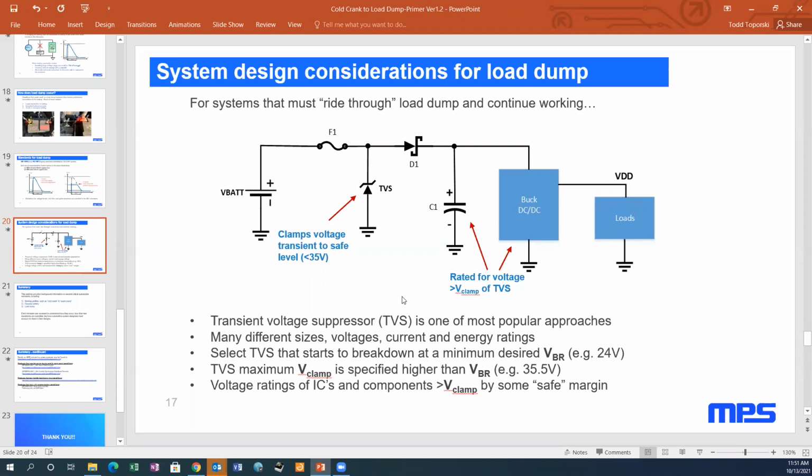That's really a difficult question to answer without knowing the waveform of the load dump it's trying to clamp. For example, you may see in a data sheet that a specific TVS diode will start clamping at 28 volts. So that's where it'll start to shunt small amounts of current. But then as that energy pulse continues to get larger and it's a whole lot of current at that time, this device will start heating up.